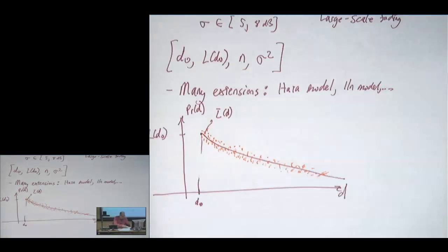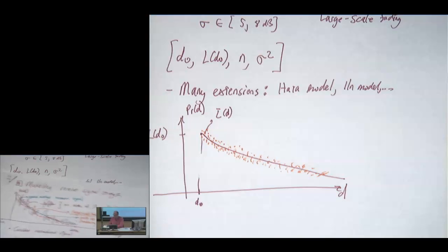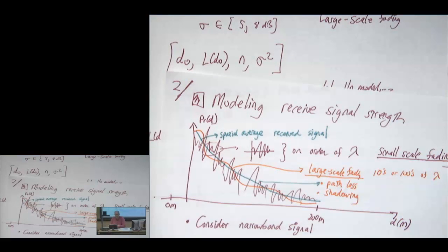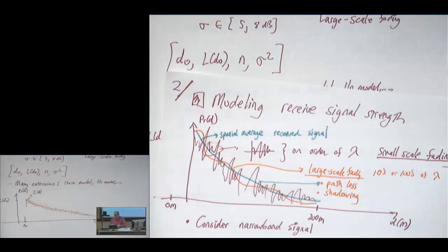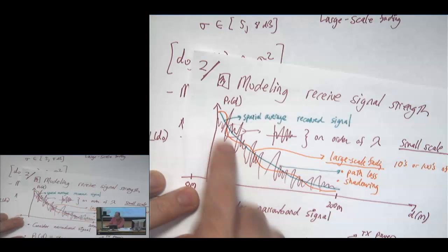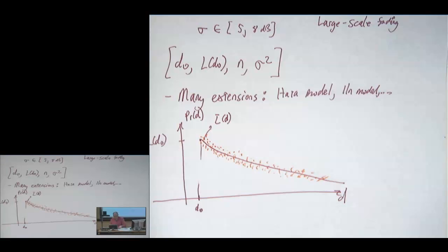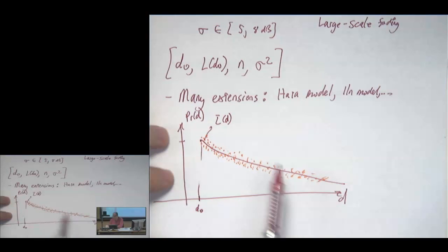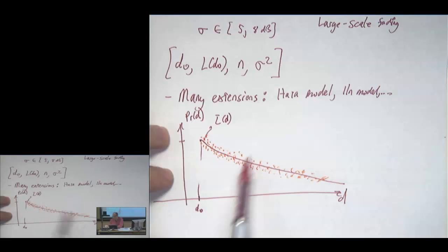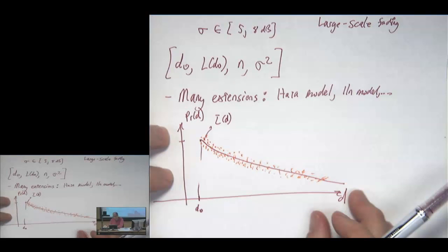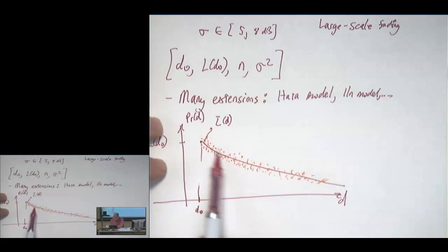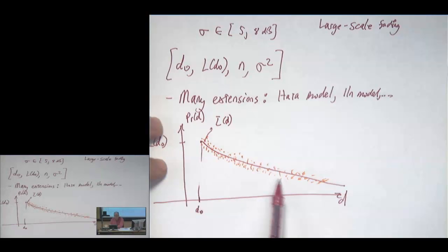That is not exactly the same as my nice smooth curve, because I didn't capture the correlation that happens, as I mentioned, like when you're behind a building for a while. But it gives the same average variation. Now, if we look at measurement results, and I didn't bring a paper that has them, real measurement results have such a cloud. You make the measurements at 100 points, and they don't fall on top of this line. They fall all over the place, but they roughly decay with distance. Effectively, the variance of this large-scale parameter captures what I call modeling error, or fit.